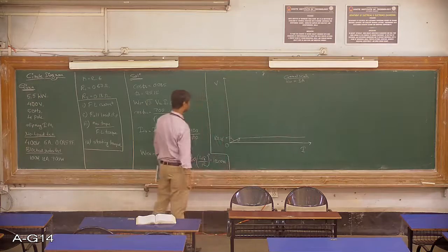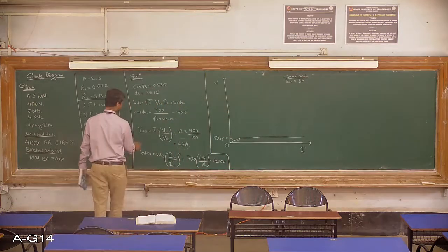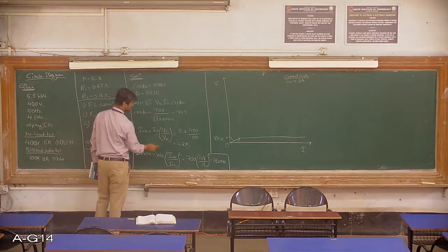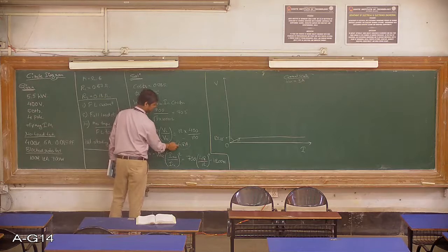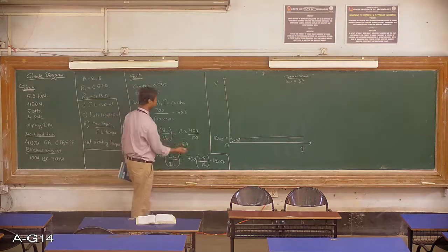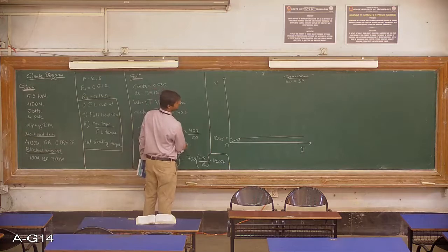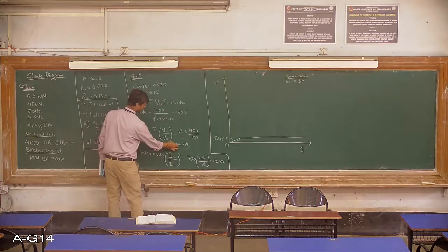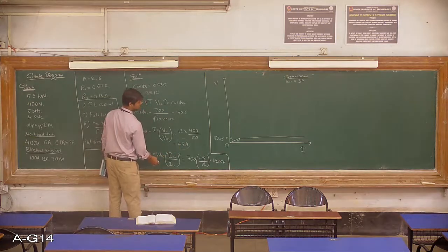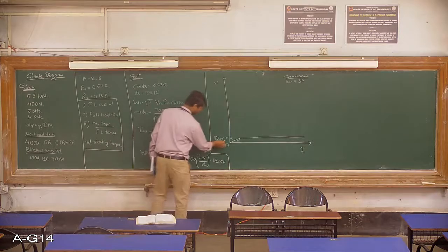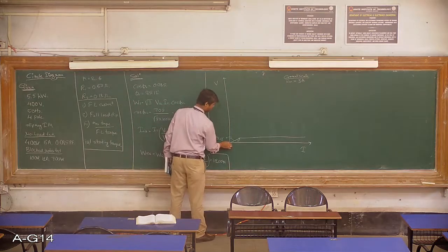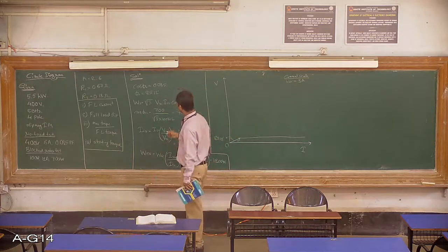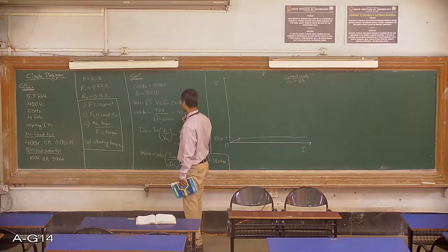Okay. Now after this I should be drawing this ISN, once again from the starting point or the origin, that is 48 amperes. Now this is in amperes, convert this into centimeters using the current scale. 1 centimeter is equal to 3 amperes, that means ISN 48 amperes divided by 3 is 16. So starting from the point O, draw a line of 16 centimeters with the angle 70.3.